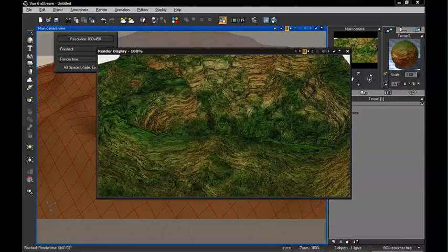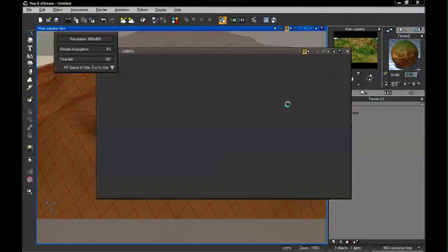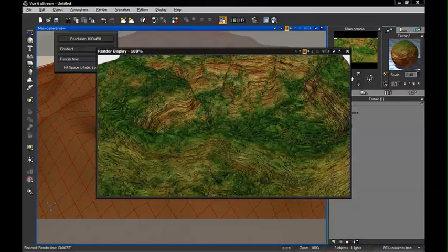And we can see, although it's not a very realistic looking surface, it is very interesting. It should give you a very good idea on how these different attributes work. One thing I do want to do is scale this down, which is not going to modify the slope range that we have for the distribution of color or the bump, but reduce the overall scale of each of those individual textures, but it will still be distributed the same. So we can take a look at a render for that once this finishes up. And we can see a little bit more detail. Overall, some of the surfaces might be a little bit too large, but it does look pretty good.